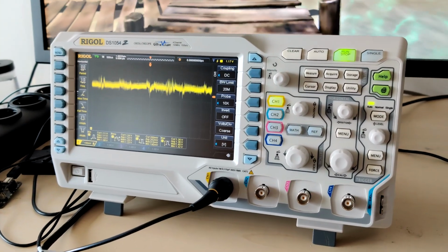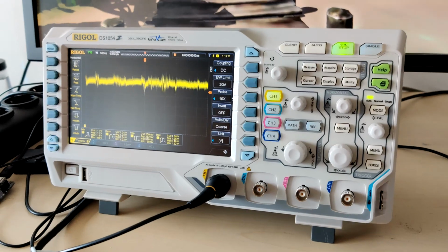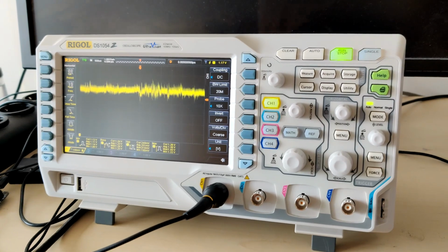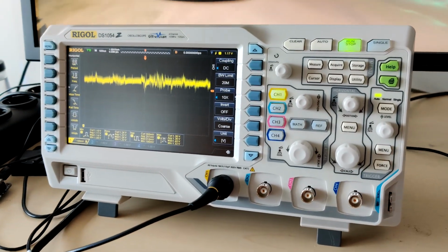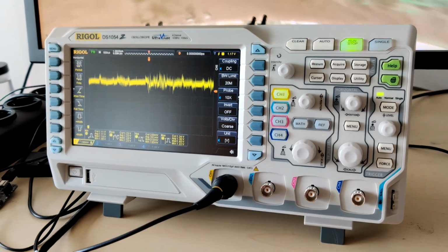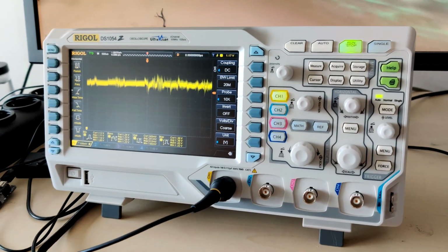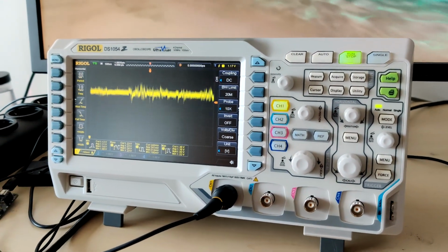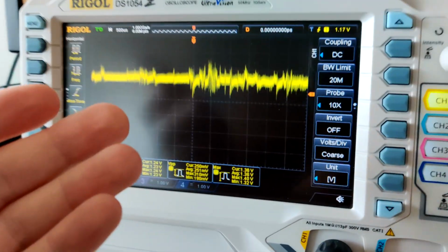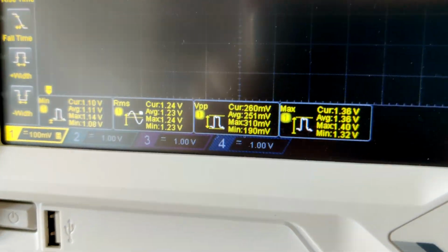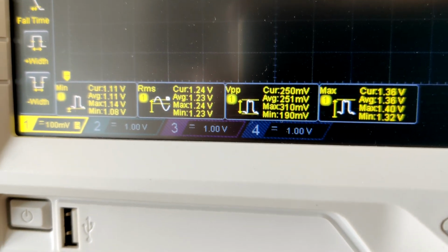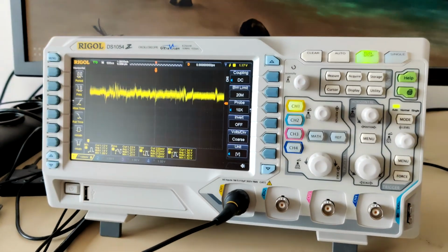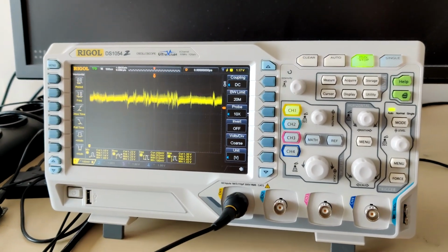Now I'm going to probably put a GTX 480 power board on it, which has 6 phases. So that could potentially drastically upgrade the voltage regulation quality. That plus me putting a lot of capacitors on the card and doing whatnot I can do to improve the card's overclocking capability. And using this oscilloscope, I can now visually represent, with very precise number measurements once I actually figure out how to hook up my probes with this, how good that VRM is and how much better an e-power can actually be.